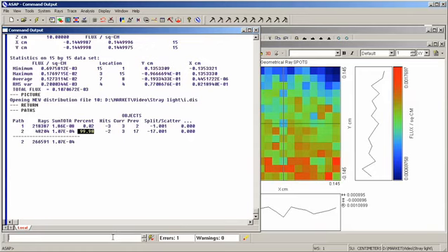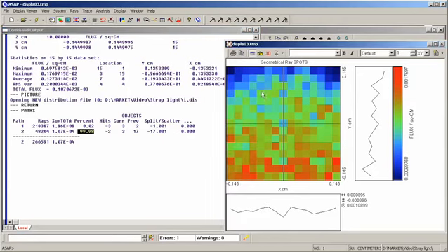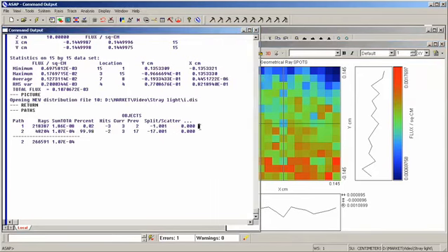Thus we see how ASAP is able to do efficient stray light calculations, do an accurate BSDF fit to realistic BSDF data, and how ASAP shows us not only the total stray light irradiance on the detector, but also ranks the stray light paths by importance and the total power that is on them, so that we can find out those paths that are most important and find out where the problems are so that we can solve them and improve our stray light calculation.